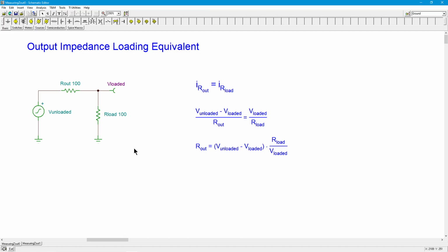Now, word of caution: if you're going to do this across a frequency range, you're probably not going to use a standard cheapy DMM, because a lot of times those things are limited in frequency. If you're lucky, it'll go up to a kilohertz. You put in a 10 kilohertz sine wave, who knows what you're going to get. I've seen some meters that don't do well over about 100 hertz. So, all depends on what you spend.